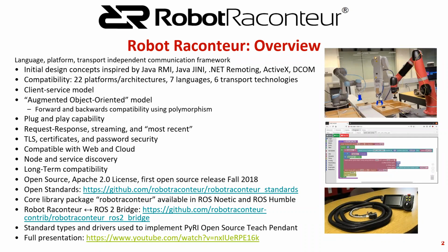It has TLS for security, which is the standard encryption method. It has certificates for the nodes to provide authentication that you're talking to the correct device, and has password and certificate security. It's compatible with web and cloud systems, so it's able to work with HTTP servers and web browsers. It has discovery. It has long-term compatibility. That's one of the main goals: to make sure that we can talk to devices over long periods of time, since industrial equipment often lasts for decades. So you want to make sure that you can always talk to your equipment.